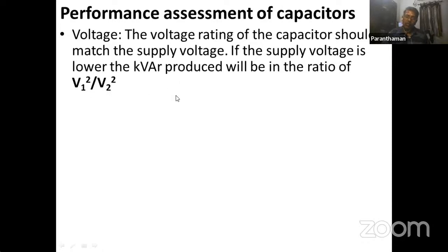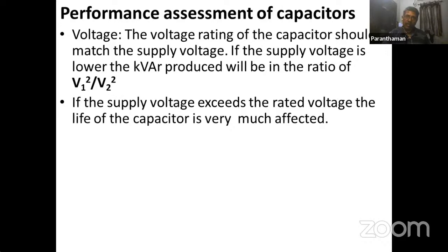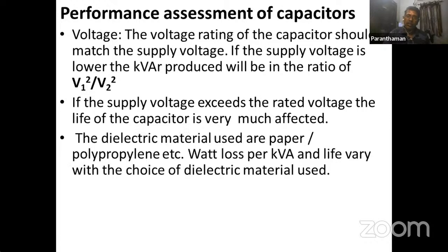We may use one problem we come across at the end. But in this slide, you must keep this in mind. If the supply voltage exceeds the rated voltage, the life of the capacitor is very much affected. What you are procuring is at a rated voltage and the supply voltage is high. This will reduce the life of the capacitor.